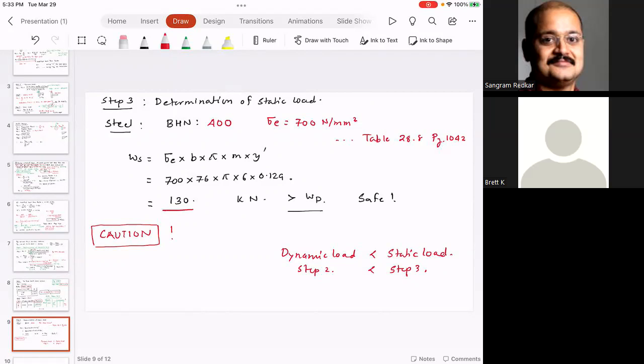It is not really required, but if you want to eliminate the iterations, you can do this. But sometimes when you go to industry, cost is one of the concerns. At that time, you want to balance the cost versus the size versus the dimensions. So you may be asked to choose a gear that does not have expensive or extensive heat treatment. You can just go with a BHN of 150 or 200 or 240, and I think that would still be sufficient in this problem.